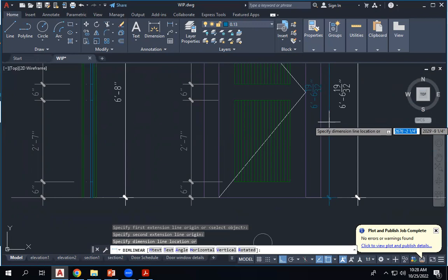But make sure. But here, are you taking 6 8, the door height most probably, or 7? The taller person. 6 8. Yeah. So after the framing, it will be reduced again. It will be 6 6 almost. You will lose 2 inches of the top for the frame. If you want more, then the door height, just change it to 6 8 or 7. 7, then it comes around 6:10.